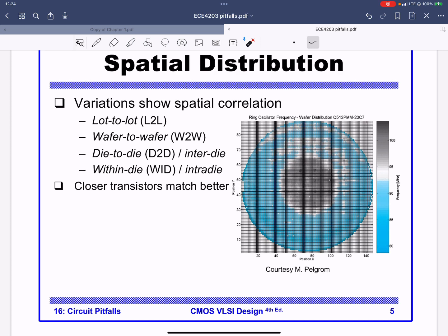And then different wafer lots, as you can imagine, if you process a set of wafers today compared to a set of wafers 6 months from now, things might have changed at the factory. It could be that the calibration values of the manufacturing parts have changed. Processes tend to drift over time, and a big part of what the manufacturing engineers do is to try to keep them on track or bring them back to the baseline. But each time you do a run, things could be different.